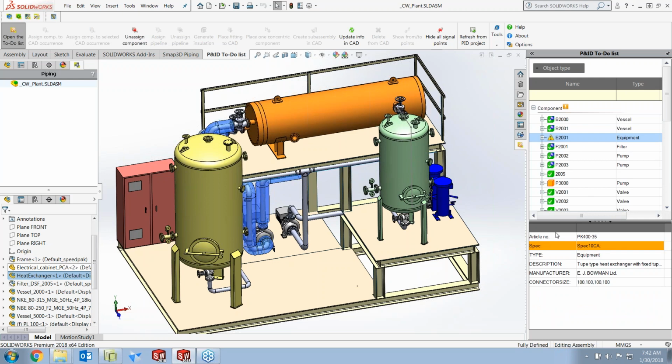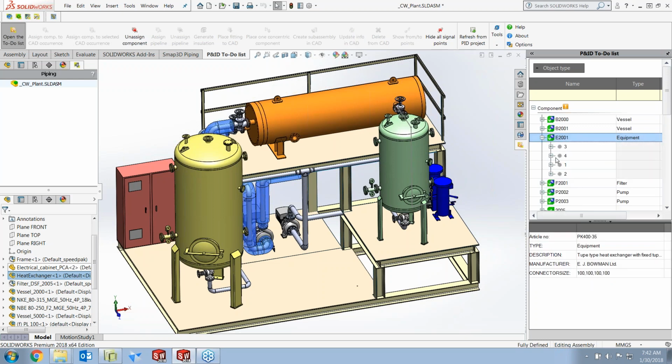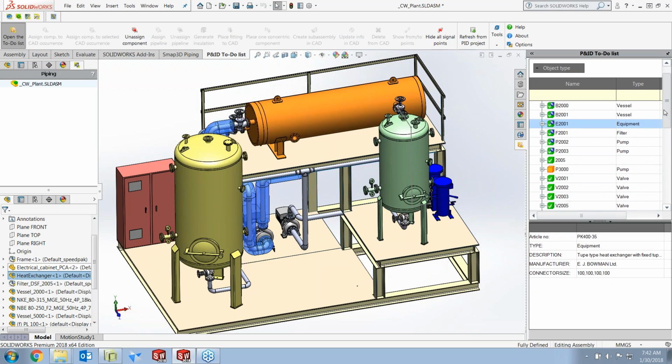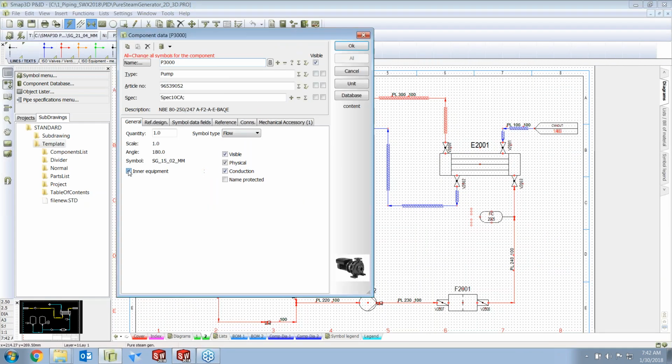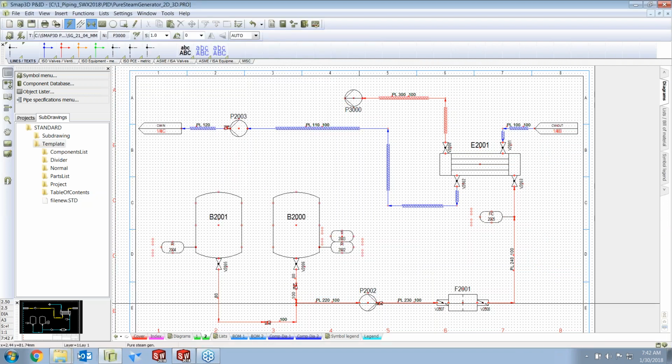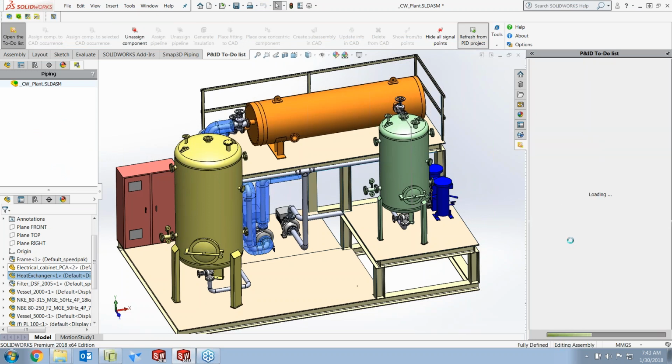And we'll notice there's some more information here. So there's a new pipeline used in Spec 10CA, and it's 100 millimeters. All right, so I'm just going to update all my connections there. And so now it knows all the connections that are being used. Okay, we got that new one that just came in with that valve. Also, in my list, you'll see that I did not put the checkbox. I forgot to check that off. So it did not put a blue dot on there, but if I just come back over here and refresh this again, we'll see that this will pop in. And then we can go through and create our pipeline.